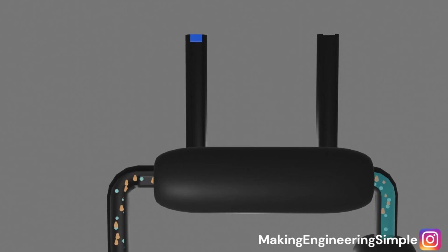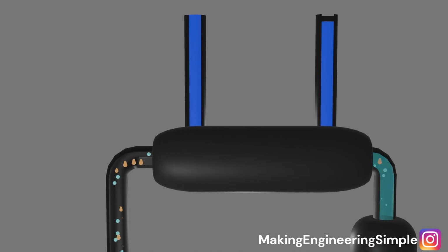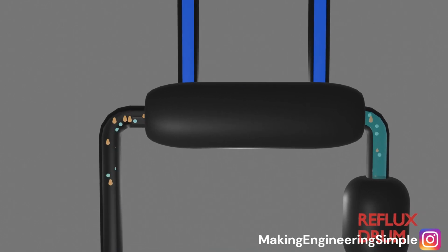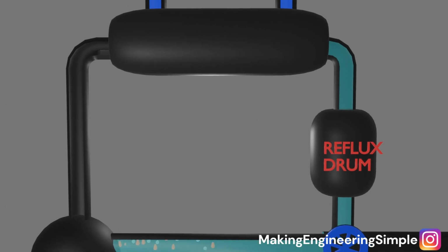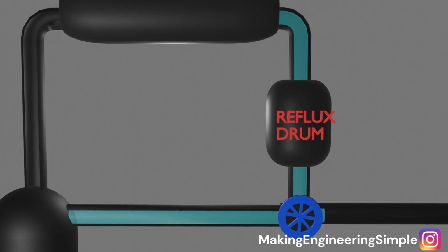Cold cooling water flows through the tubes, pulling the heat out of the vapor and condensing it back into a liquid form. This new liquid collects in a reflux drum. From here, the flow is split. A portion is recycled back into the top of the column as reflux to help cool the rising vapors. The rest, if it meets our strict chemical specifications, is drawn off as our final overhead distillate product.